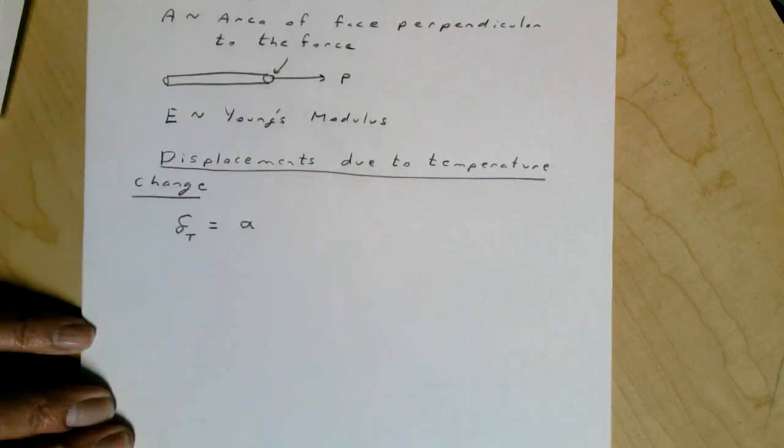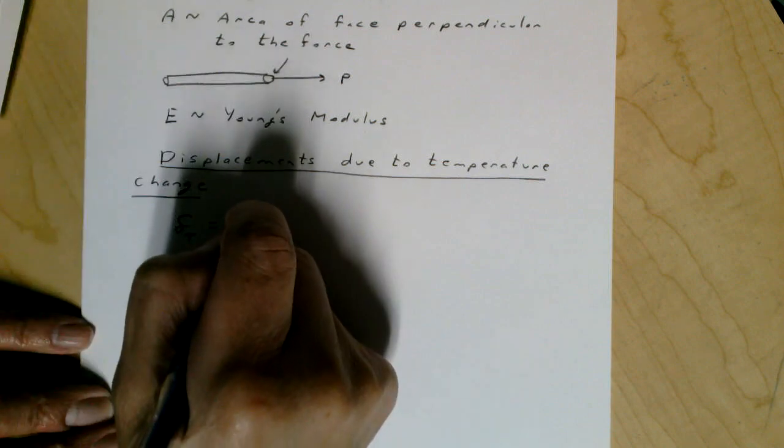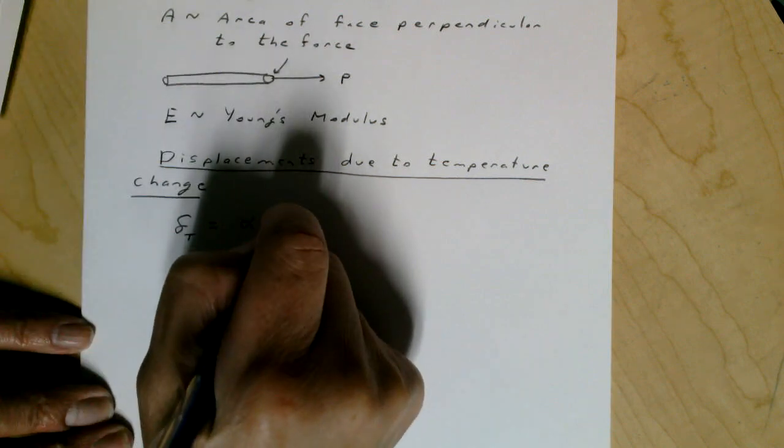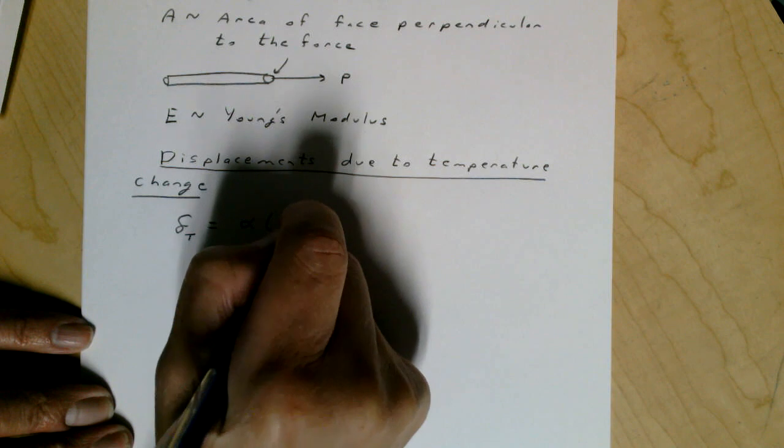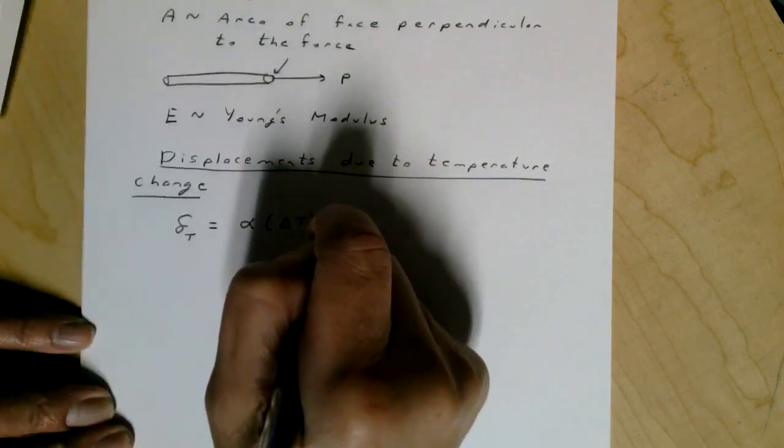It's the linear coefficient of expansion times the change in temperature times the length of the part.